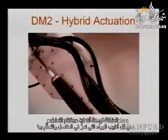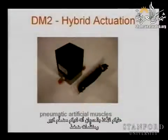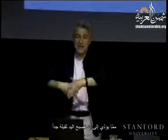Now the problem with this is how can you manage all these tubes of air that are going to go to the joints and control? Every joint will need two muscles. Because you realize you have large amplifiers, pressure regulators, and you cannot think just I'm going to take all these tubes. You will have a lot of them, and your arm will be very heavy.